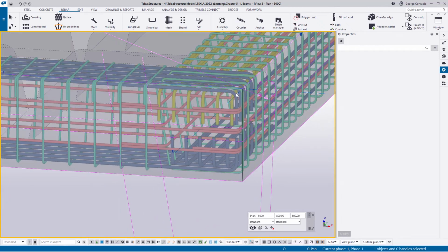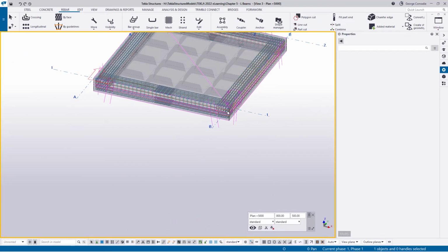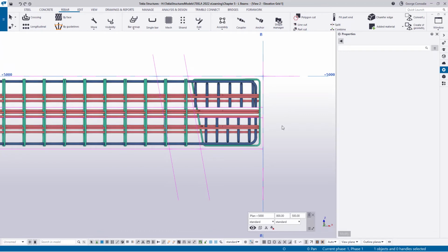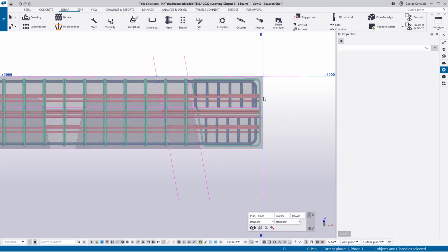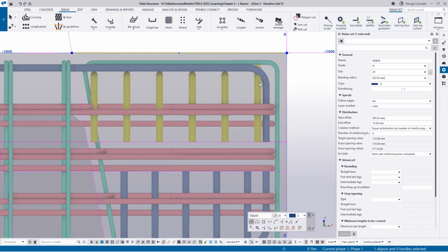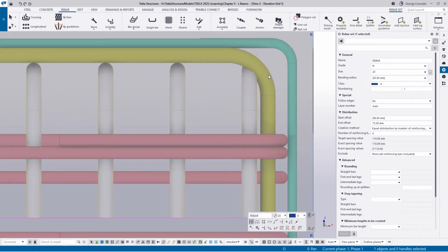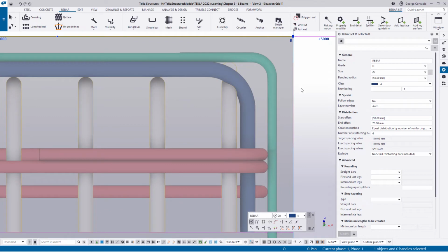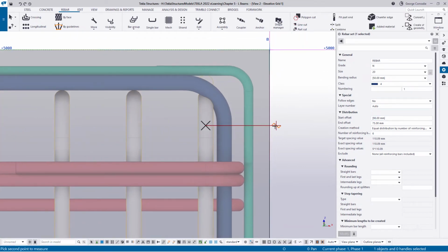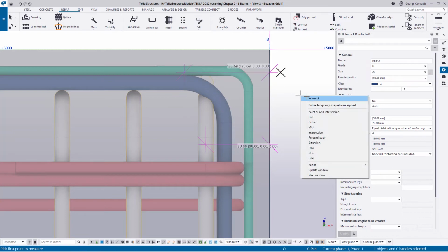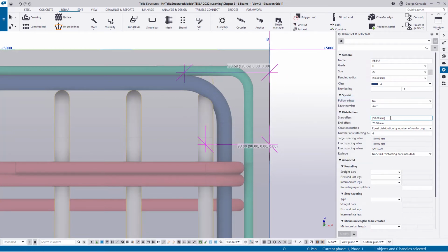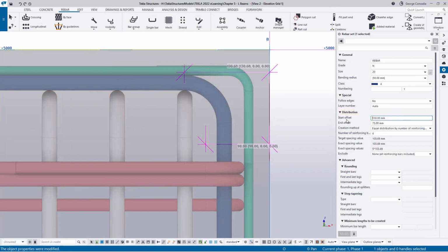Now what we need to do is address this. If we look at our view on grid 1, a redraw, we can see this is the issue we have. If we click on this, we also have that issue that we need to address, and that's a very easy fix. First I want to fix the spacing. If we go to the spacing here, we're looking at, if we take a dimension here, from there to there, we've got to change 98, and we want to change it to 130. So if I click here, I can change 98 to 130, and that fixes that up.